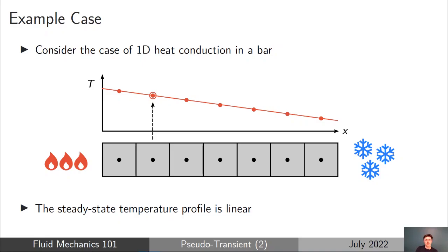The reason I'm going to think about solids first is that the only boundary effect we need to think about is the propagation of heat from one end of the solid to another. That's generally because the solid isn't moving, it's often a stationary wall, and the only thing we need to think about is the solid heating up and transporting heat across it. So this will be a much simpler case for us and easier to derive a characteristic speed for how the effect of thermal boundaries propagates through a solid element.